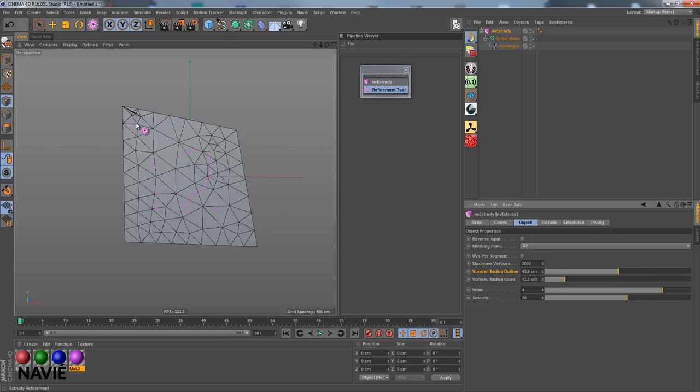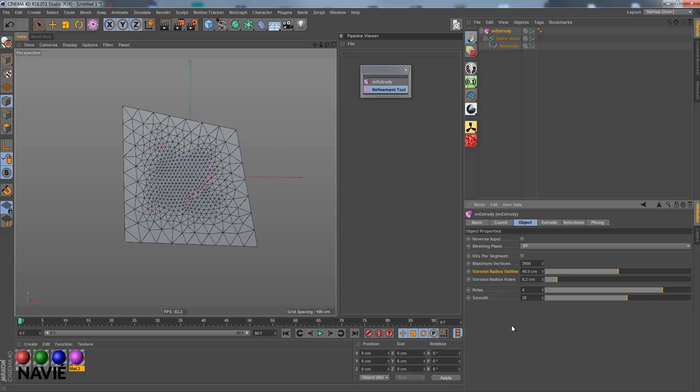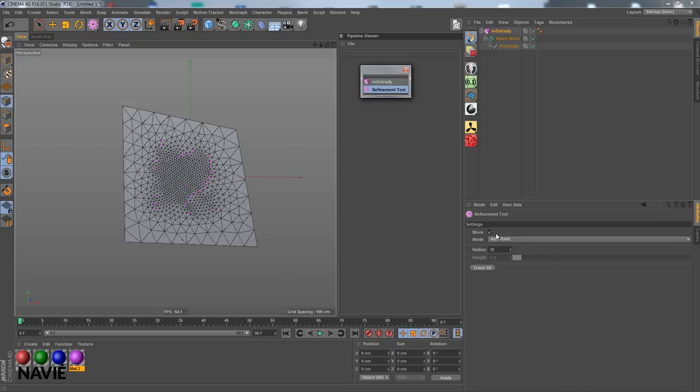You just have to be aware that you need to move the points outside of this so it can freely adapt the sizes down to the actual refinement. This happens the same, for example, if you have a very big radius at the outside boundary and you want very low radius down there, it wouldn't work.